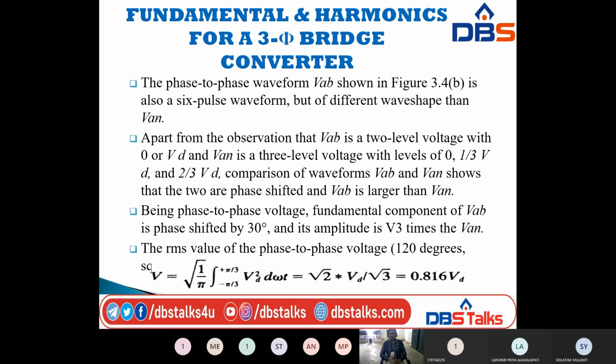Okay, being a phase to phase voltage, that is VAB or VBC or VCA, the fundamental component of VAB is phase shifted by 30 degrees, and its amplitude is root 3 times the VAN.